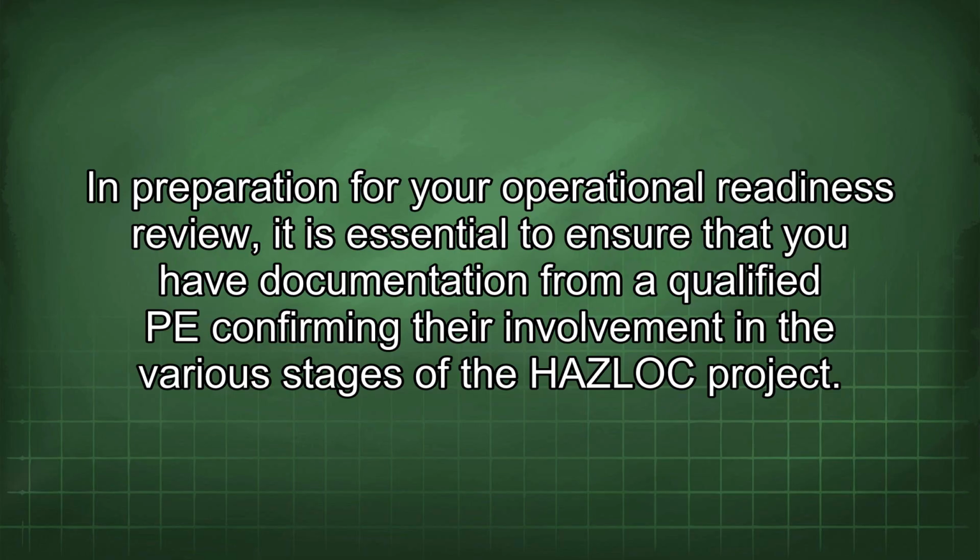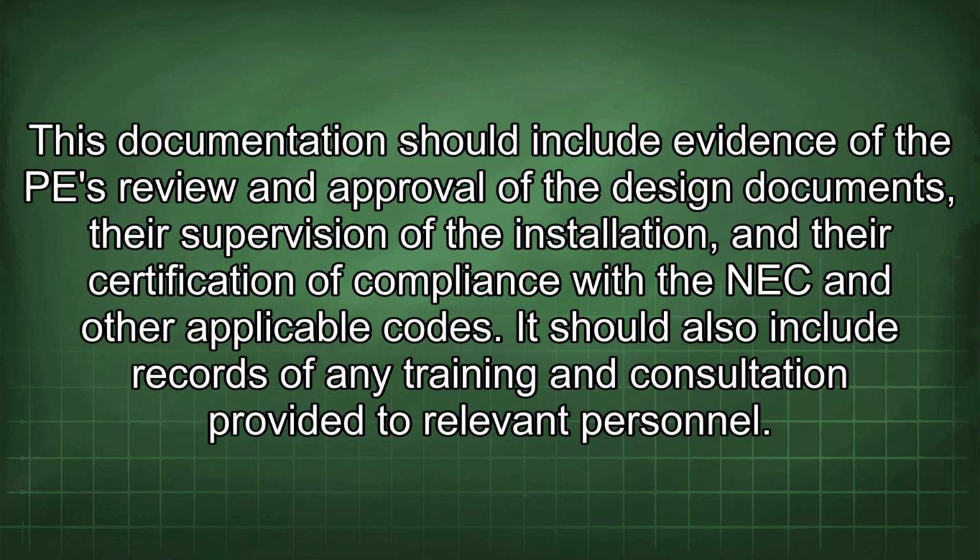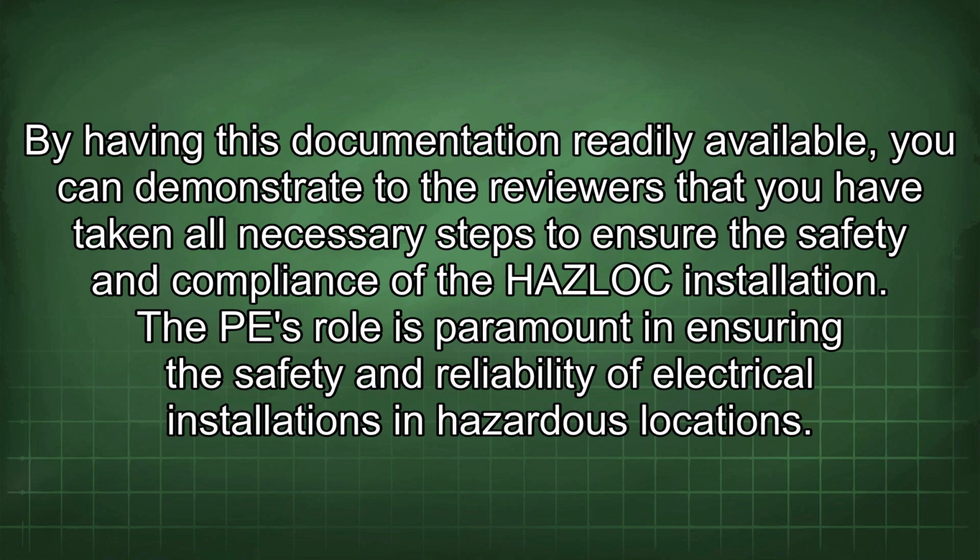In preparation for your operational readiness review, it is essential to ensure that you have documentation from a qualified PE confirming their involvement in the various stages of the HAZLOC project. This documentation should include evidence of the PE review and approval of the design documents, the supervision of the installation, and the certification of compliance with the NEC and other applicable codes. It should also include records of any training and consultation provided to relevant personnel. By having this documentation readily available, you can demonstrate to the reviewers that you have taken all necessary steps to ensure the safety and compliance of the HAZLOC installation.